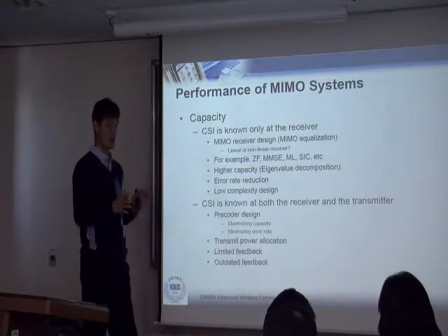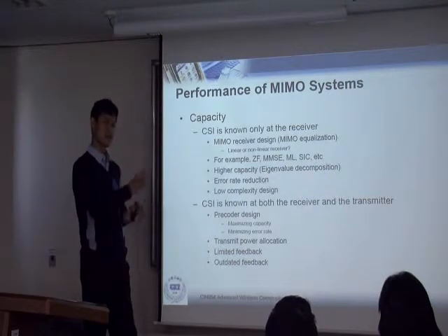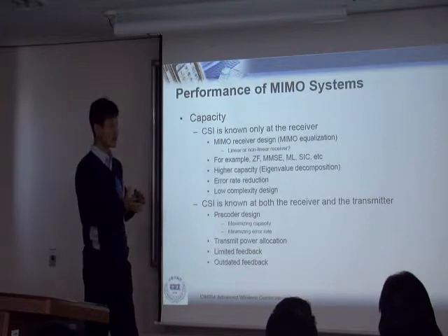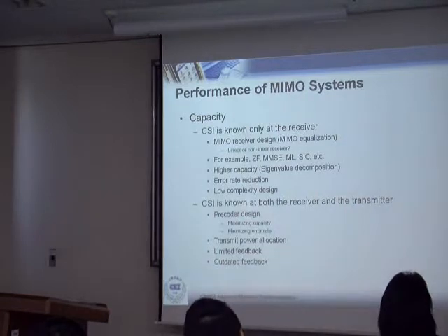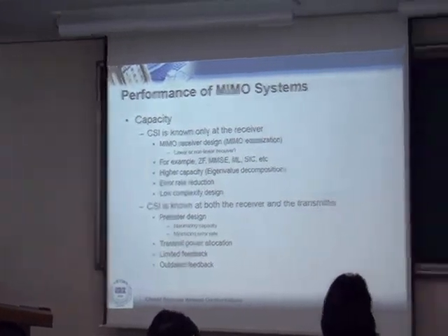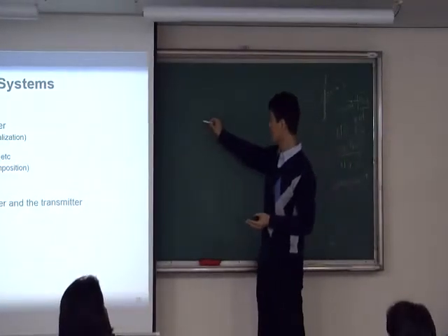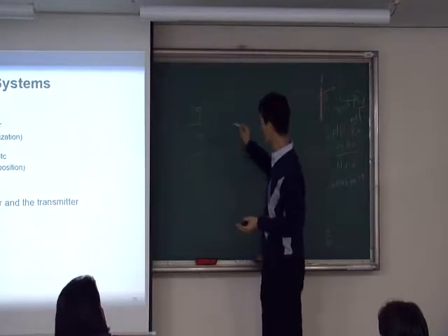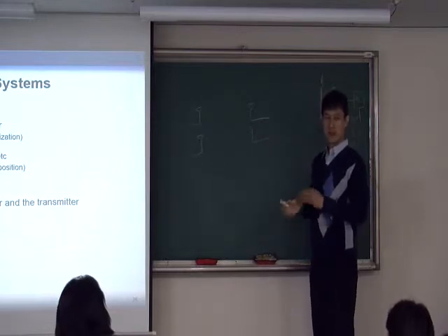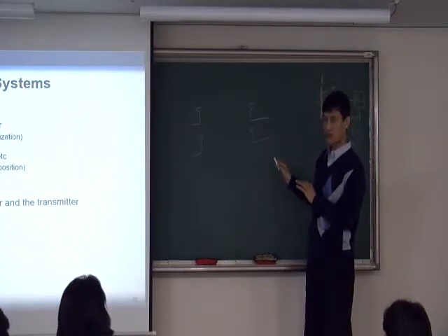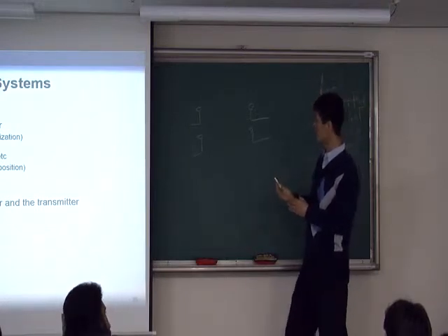When we say equalization, that basically means there is some interference, and therefore you use equalization. What is interference in this case? Since we are talking about MIMO, what type of interference? There are so many different interference types. Let's think about a very basic system, 2x2 MIMO. The interference I'm talking about in the case of MIMO is the inter-channel interference, or co-channel interference.